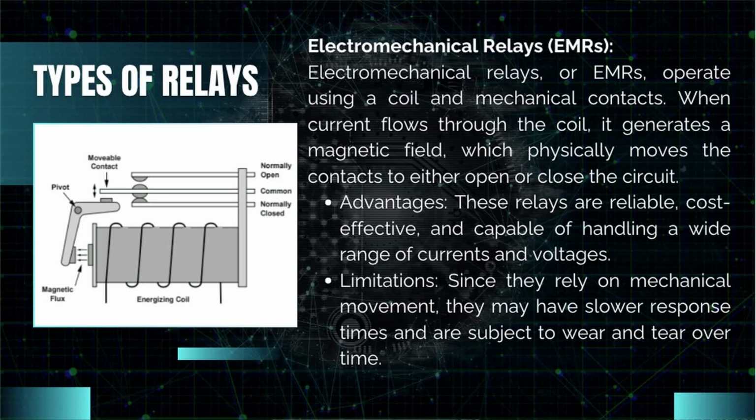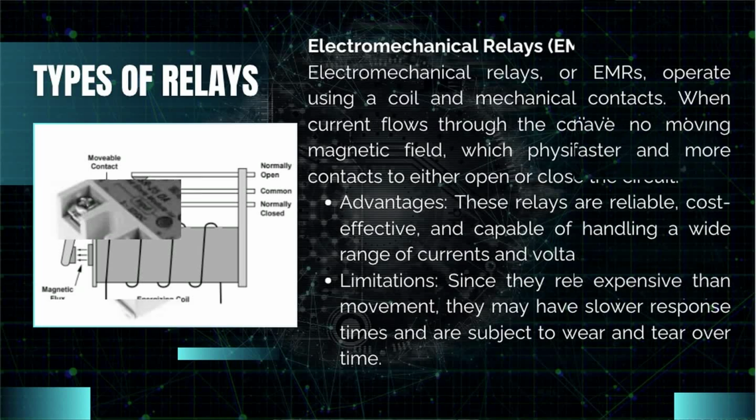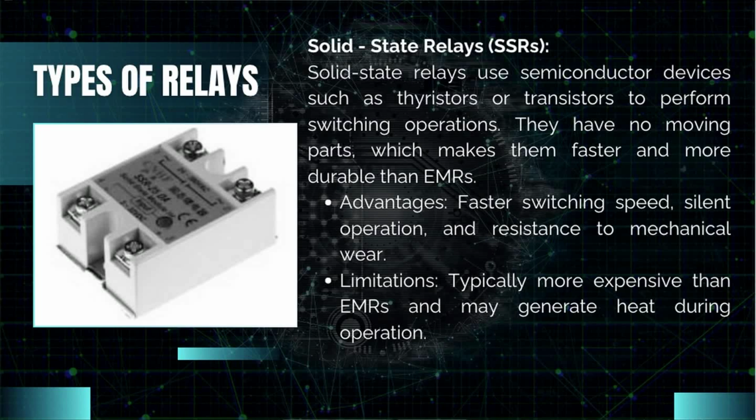Advantages: these relays are reliable, cost-effective, and capable of handling a wide range of currents and voltages. Limitations: since they rely on mechanical movement, they may have slower response times and are subject to wear and tear over time. Number 2, solid-state relays.